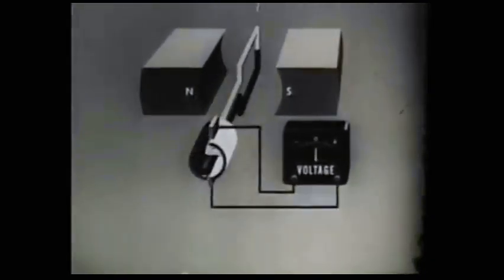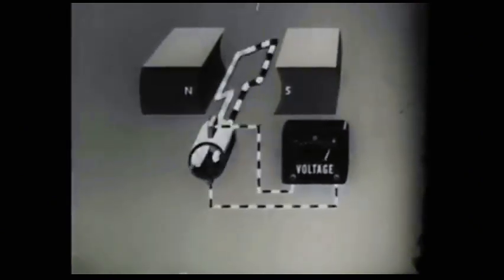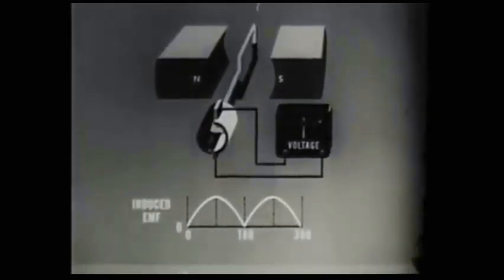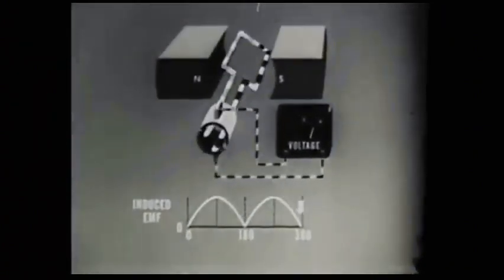The loop of a conductor, wound on a rotor, and the commutator are referred to as the armature. As the loop revolves and the EMF in the conductor reverses polarity, the connections to the load are also reversed and the current flow will maintain the same direction externally. Represented graphically, the output amplitude still varies. The DC is in the form of pulses. It is a pulsating direct current, or PDC. The pulsation from 0 to maximum, twice for each revolution of the loop, is called ripple.